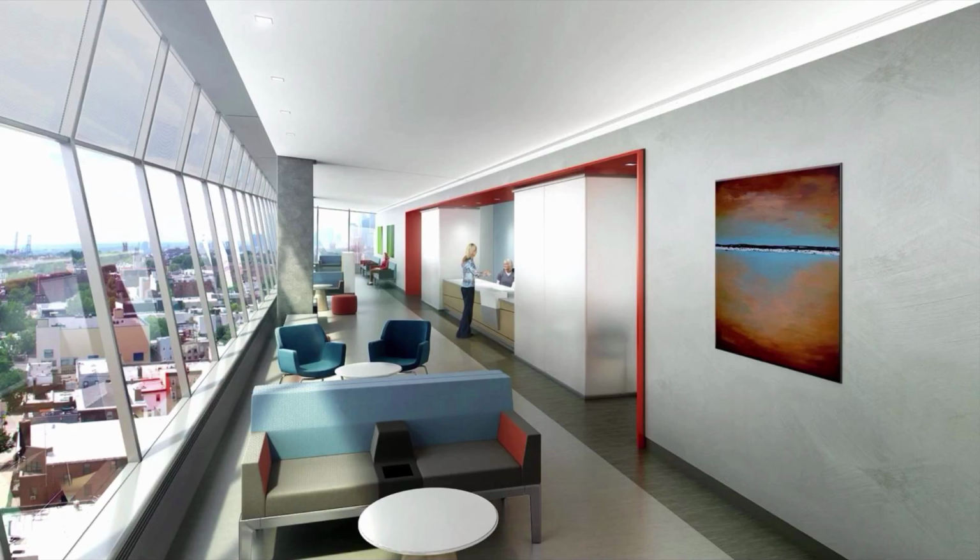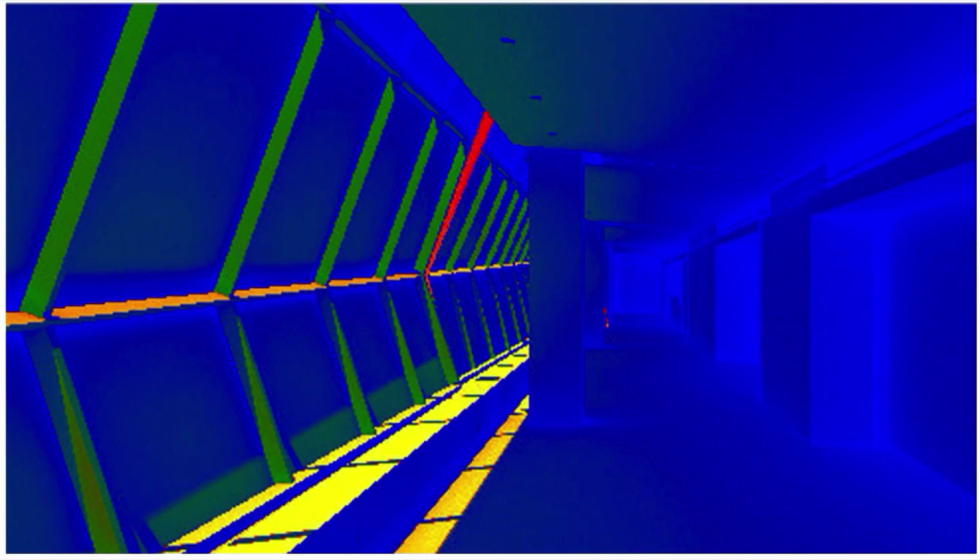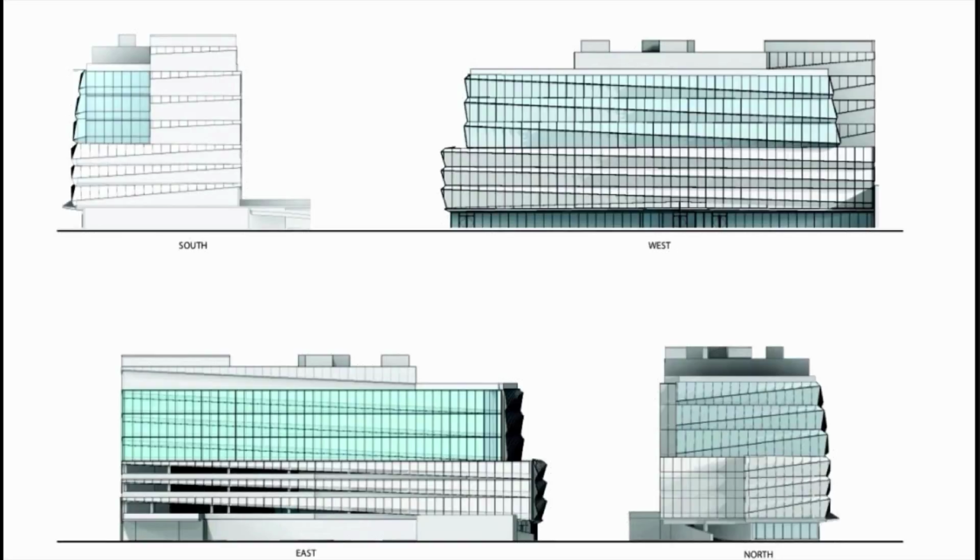We wanted to get an understanding of what happens. The basic glass material in Revit, when you populate a curtain system, has very little to no parameters of glass. So when you run the illuminance analysis, which is also done in 360 through the rendering function, you can see the surface areas are very hot. That's because the glass really has no properties.